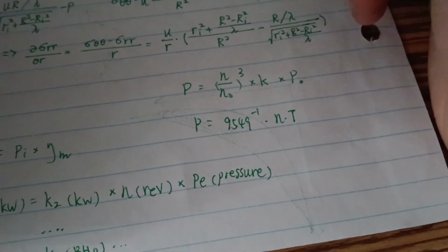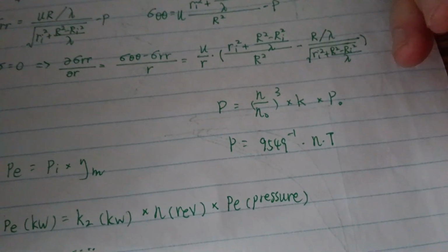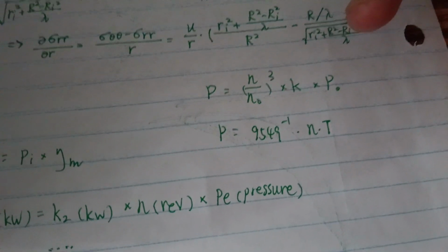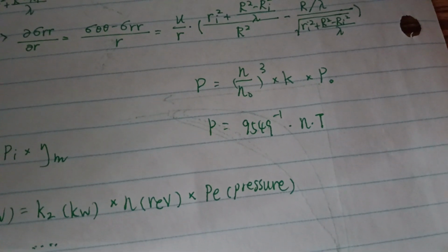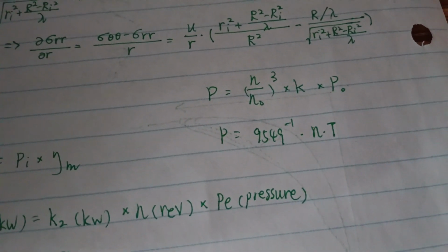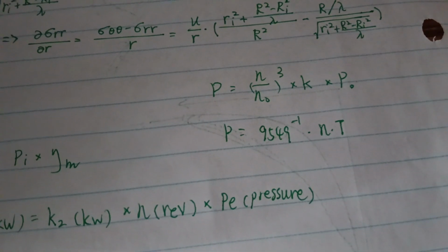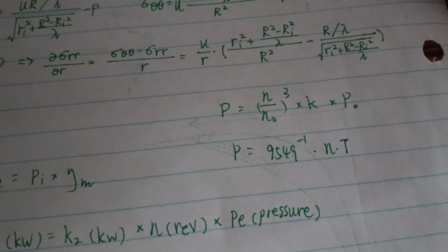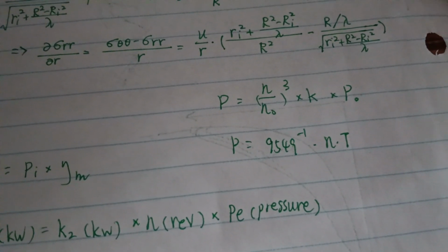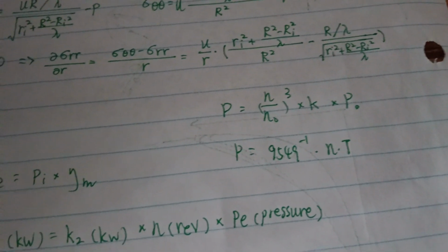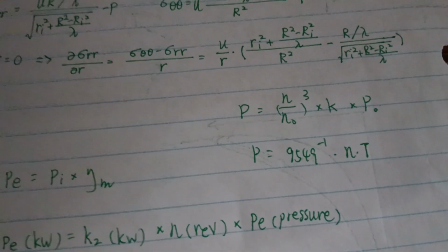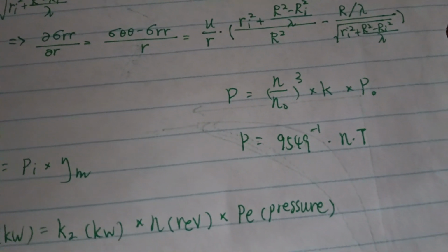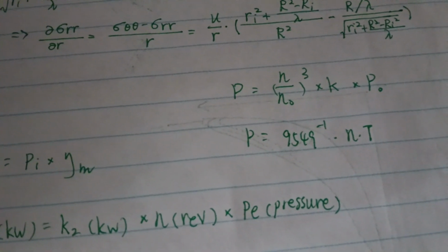The third way is just a very rough estimate from the fuel consumption rate and the specific heating value, and it should be the low heating value of the fuel you are using. Because the water won't be condensed in the cylinder, the heat which the water would release during condensation won't be released in the engine, so you will need the low heating value of the fuel.